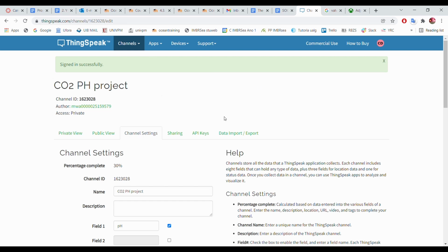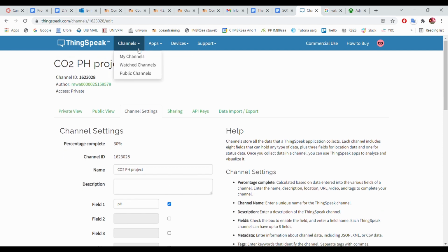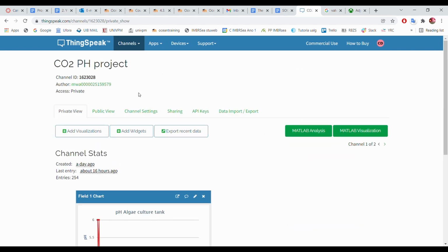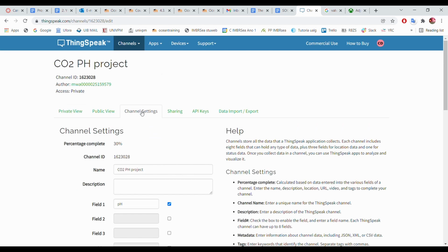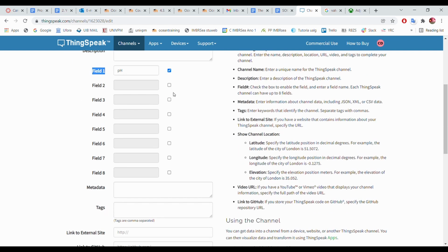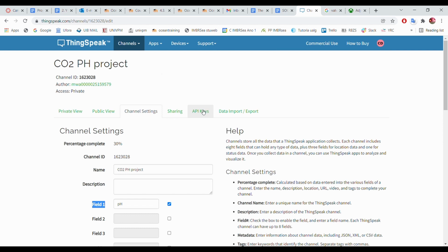So here we are on Thingspeak, and first you need to create an account. Then once you're on your account, you just press channel, my channels, and then you create a new channel, but this is not difficult, so we'll just move on. So I already created the CO2 pH project. You move to channel settings. On channel settings, you just write in field number 1 pH, click save channel, and then you will need the API keys.